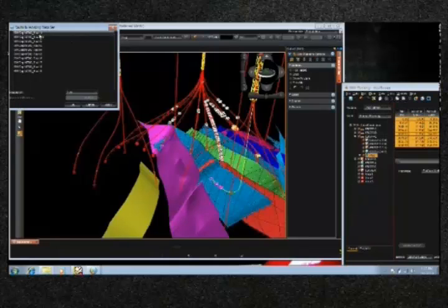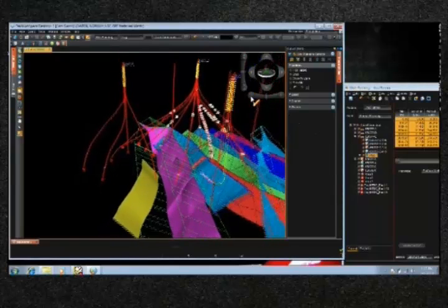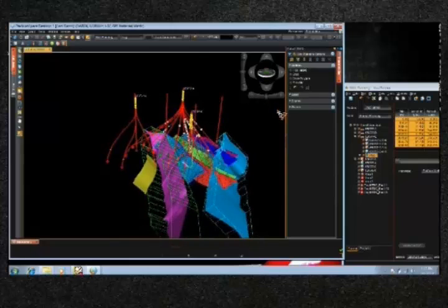To do this, we can quickly create what we term as hazards from some of those faults. Once we've selected the faults that we want, the application then creates a mesh zone around those fault planes, and this will be identified as a no-go zone. What the application does then, as it cycles through the values, it will remember not to generate plans that intersect any of those planes.